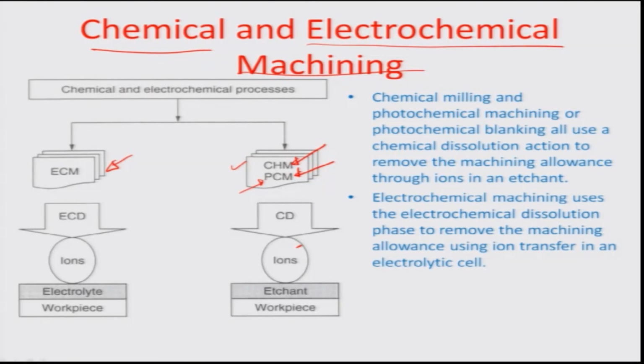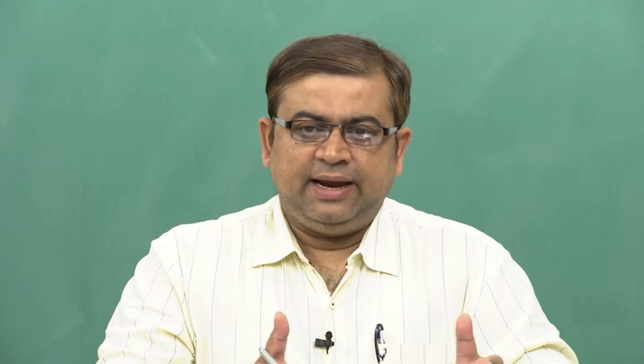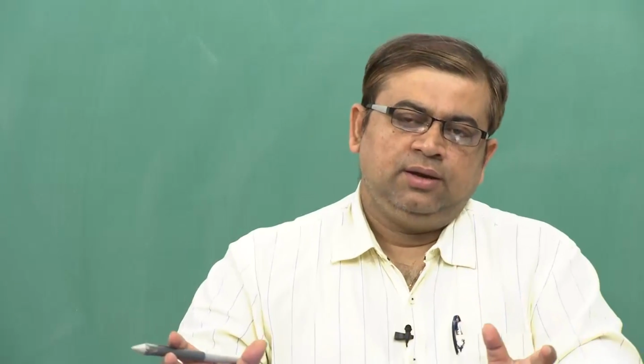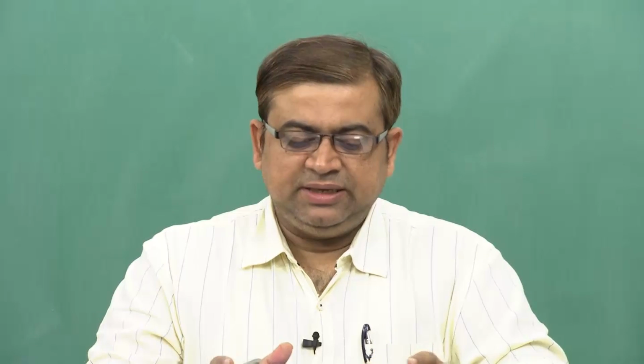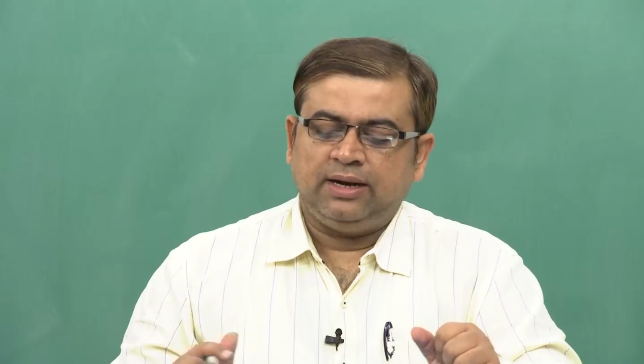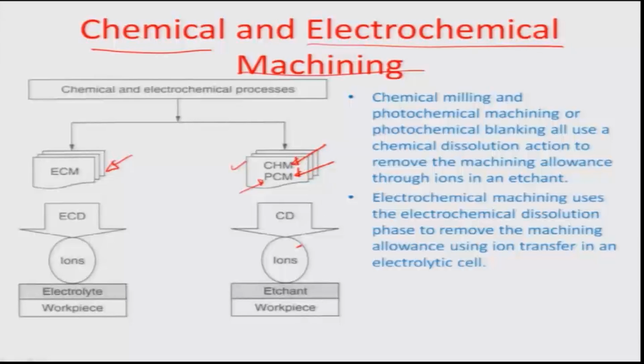So, you have some electron transport going on with the chemical process, and typically these are redox chemistries where something gets oxidized and some other material gets reduced, and there is some kind of a redox couple being formulated between the two electrodes, due to which there is a driving of either the metal going away, which is known as electrochemical machining, or the metal being deposited, which is also known as electrochemical deposition. So, we can use either of these processes to create a wide variety of machined surfaces using chemical or electrochemical means. There are many variants of such processes.